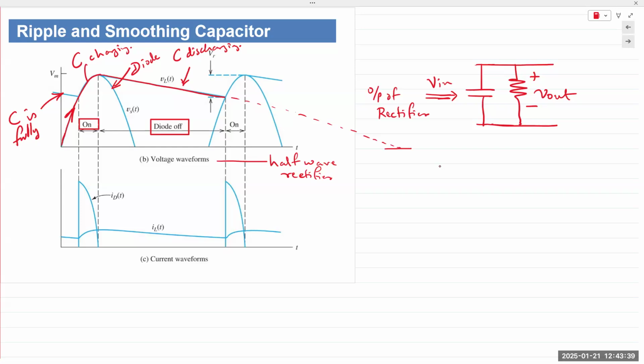So this is when capacitor voltage reaches 0 volts. But before it can discharge to zero, the next positive half cycle hits and it begins charging again. Make sense? Right? So the first positive peak, capacitor starts charging.